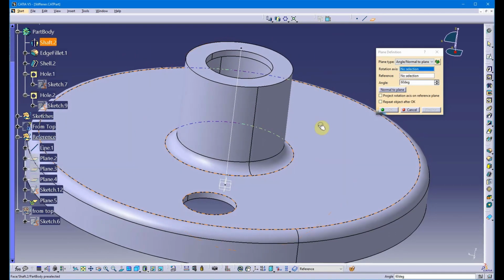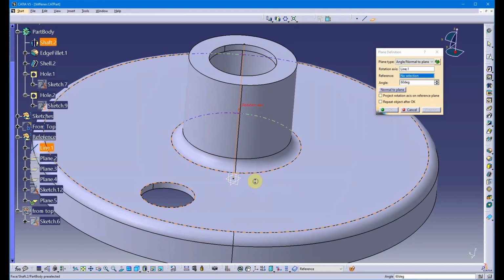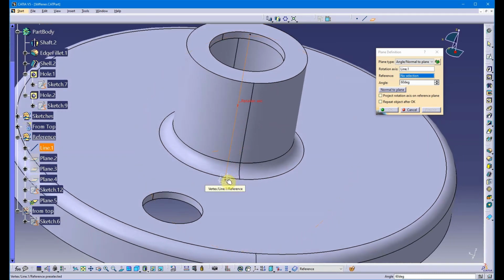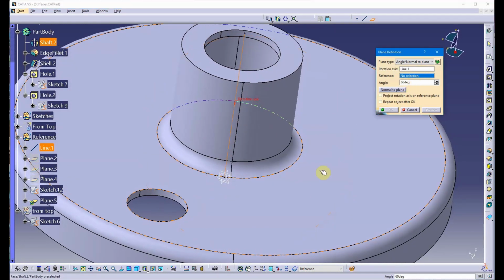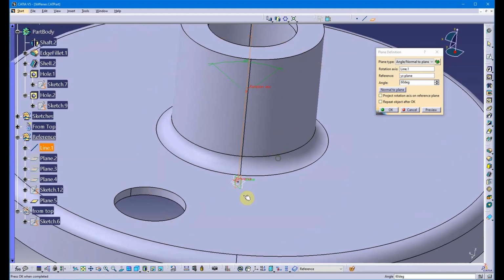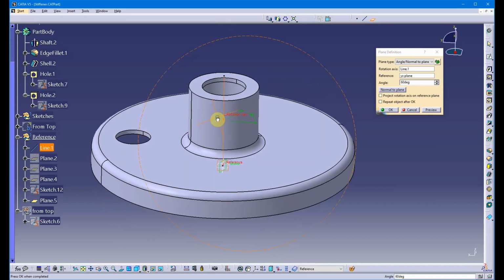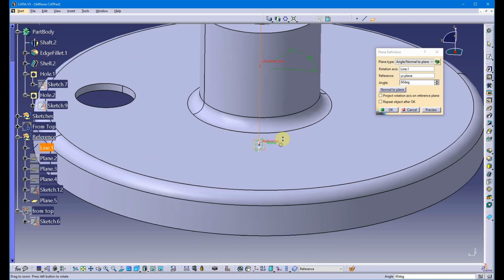Then I've got a rotational axis, which is going to be there. And that's why I created that, by the way, a line from the origin. That's a point direction line, if you're curious. So I'm going to use this as my reference. I'm just selecting whatever default reference plane that is, and I'm going to put in a 60-degree angle. Let's preview that and see where it's placing it. Oh, it's placing it here in the middle, which is fine.